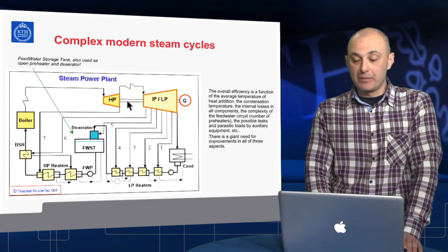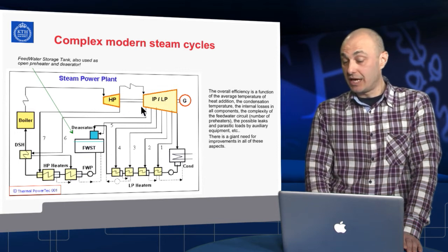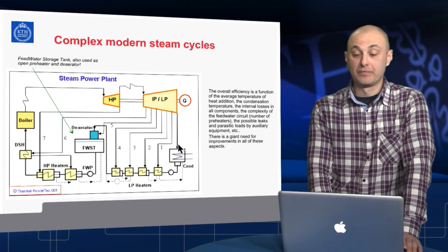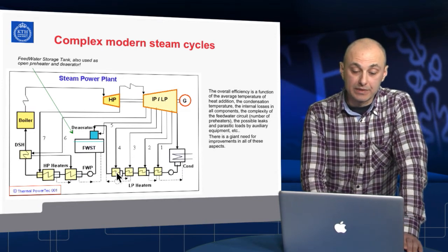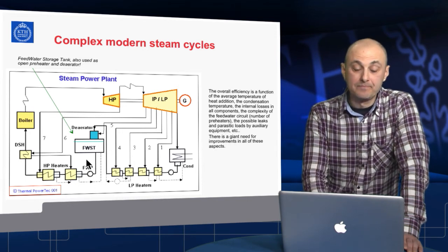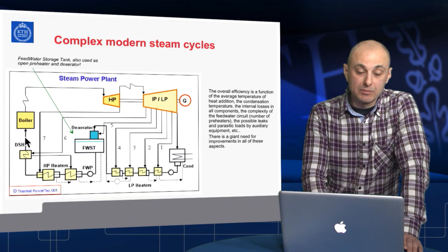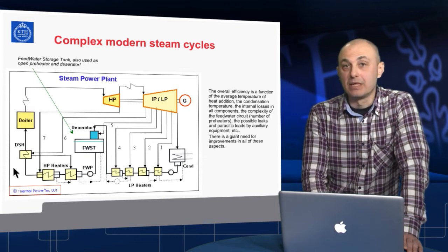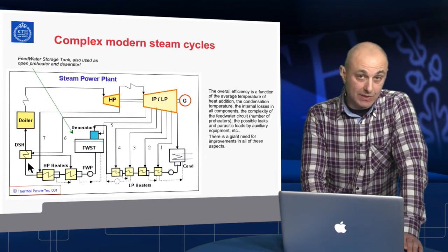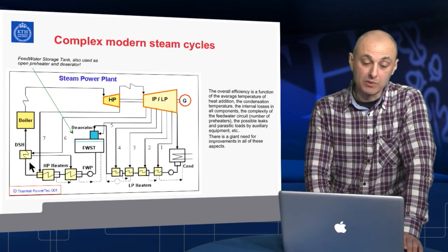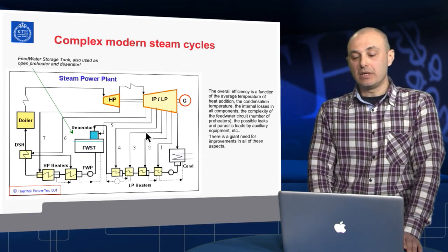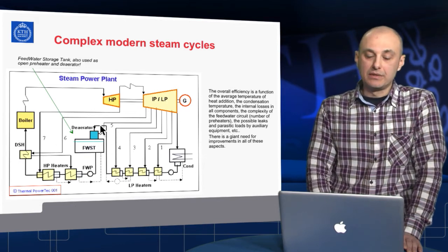The steam turbine may be situated in different shafts. The condenser will need cooling water, of course. The number of preheaters and the number of feed water pumps may be different. There might be different arrangements for internal heat regeneration in the cycle, again, to decrease losses and to decrease as much as possible the leakage of heat. And we will also need a deaerator.